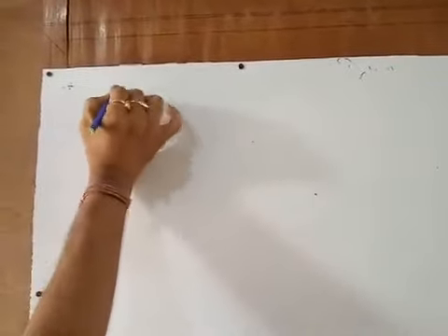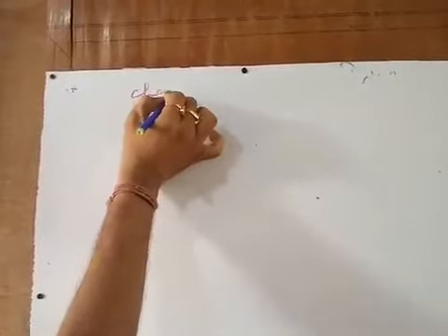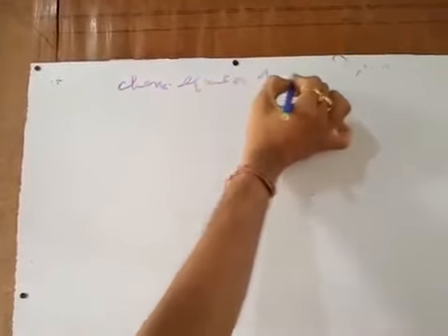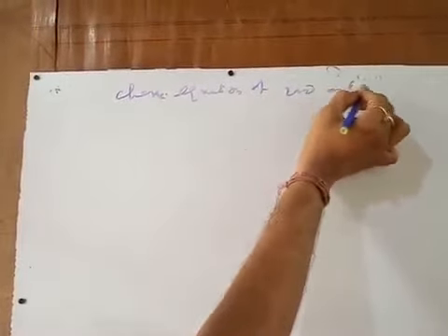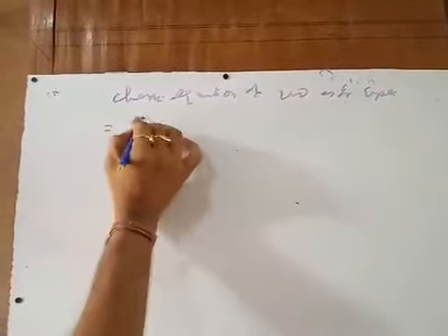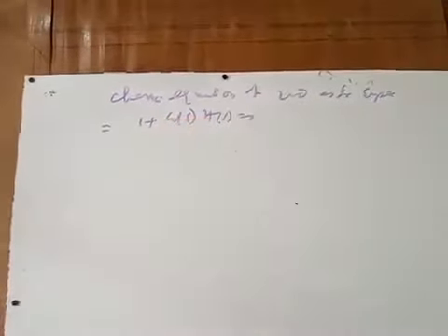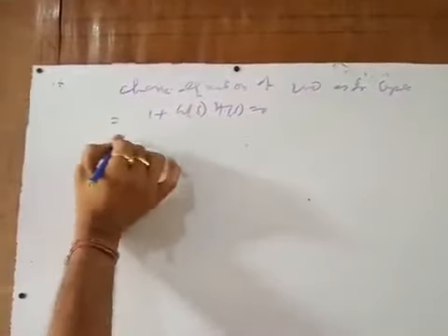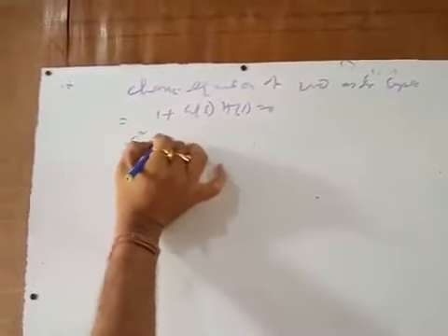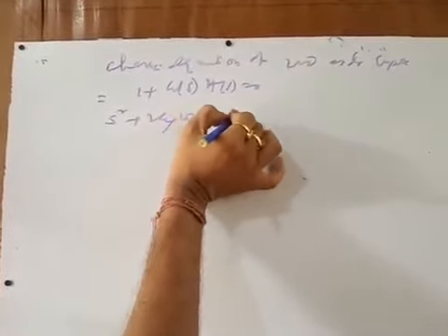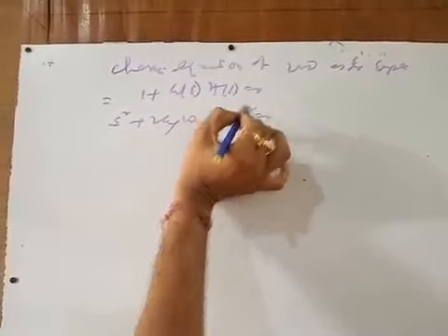So we get the characteristic equation of second order system. You see this is 1 plus G(s)H(s) equal to 0, that could be obtained from the denominator. That means s square plus 2 xi omega n s plus omega n square is equal to 0, right?